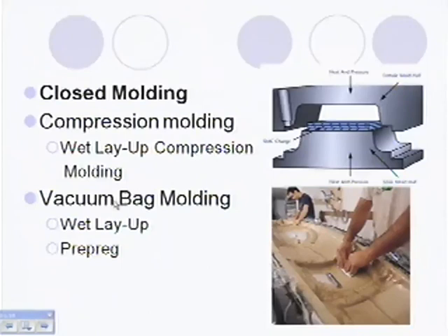And then we have vacuum bag molding. Basically it's a wet layup technique, so we saturate all the fibers, wet them all out, and then put a membrane of plastic or PVA material over the top of them, seal it off, and then apply vacuum. This is also how you do pre-preg, and that stands for pre-impregnated fabrics. These are fabrics that come with the resin already in them.